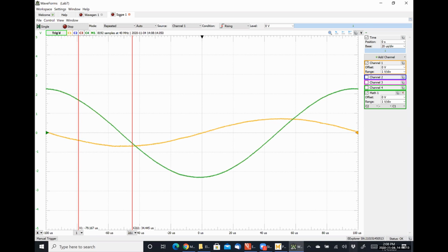All right. That's how we can actually use inductors to form filters, right? So at very, very low frequencies, inductors behave like a short circuit. What happens at very, very high frequencies? As omega approaches infinity, what does the impedance of an inductor become? Infinite. So at low frequencies, an inductor looks like a short circuit. At high frequencies, an inductor looks like an open circuit. So that's how we get a high pass filter response, which is beyond the scope of this course, but I